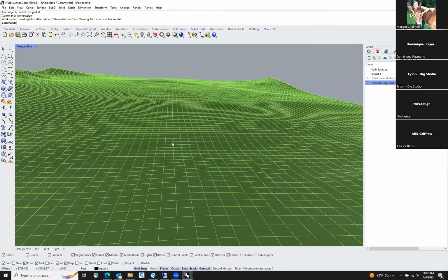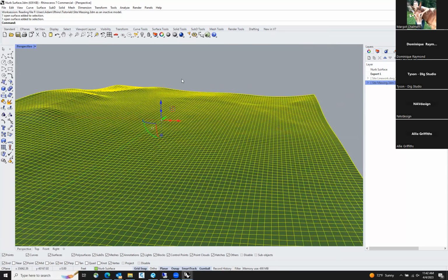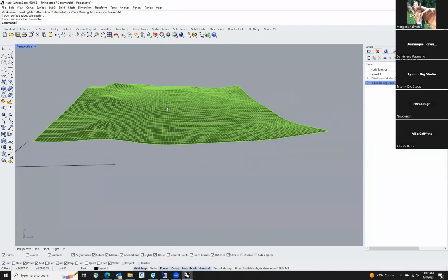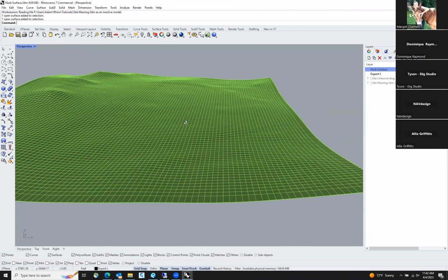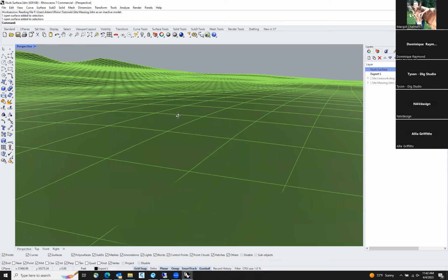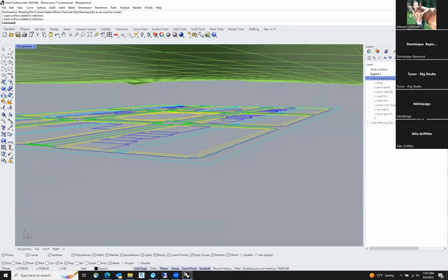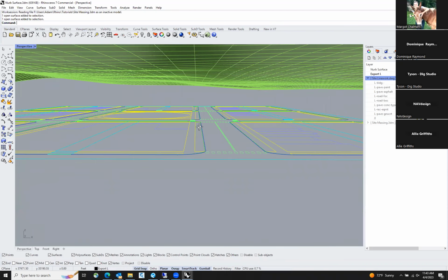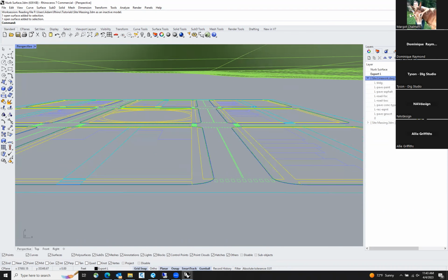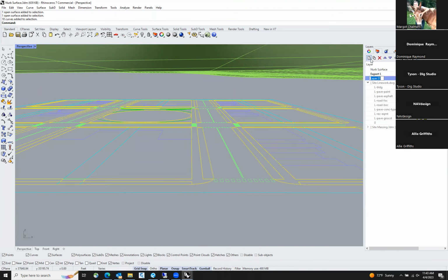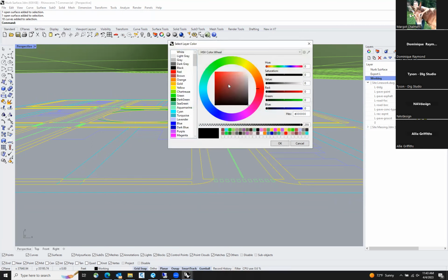So once you have your surface, and this surface is one that I think is ready to go, you can start to split that surface to start putting things on different layers. As you can see in this site line work file, there's building, there's roads, front of curb, back of curb. All of those you're going to want to render differently because there'll be different textures. And what I'll do is I'll just select these objects. I'm going to make this a working layer, and I'm going to make that working layer red.